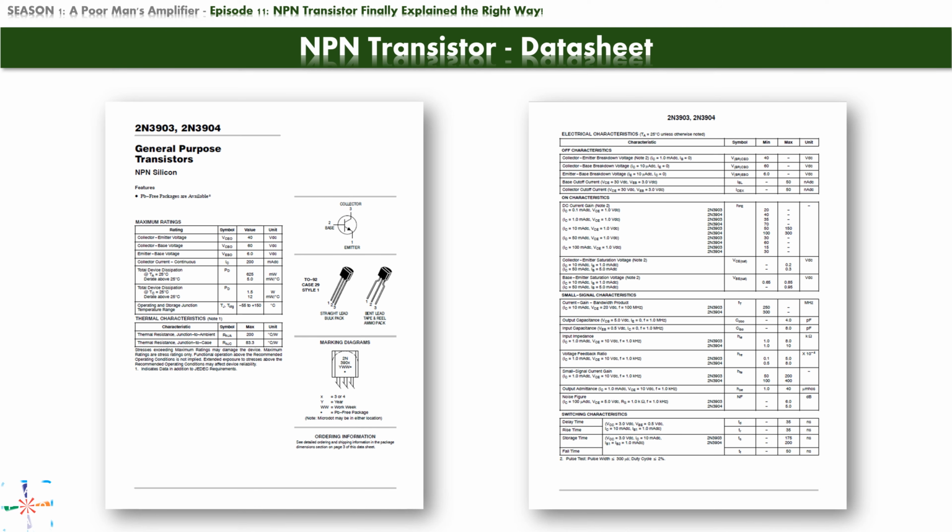Thermal characteristics refers to transistor's ability to dissipate heat, and tells us how much degrees of Celsius transistor temperature will rise, with every watt of power dissipated. Electrical characteristics represent a bunch of parameters divided in 4 groups. Each group addresses parameters related to the specific mode of work.